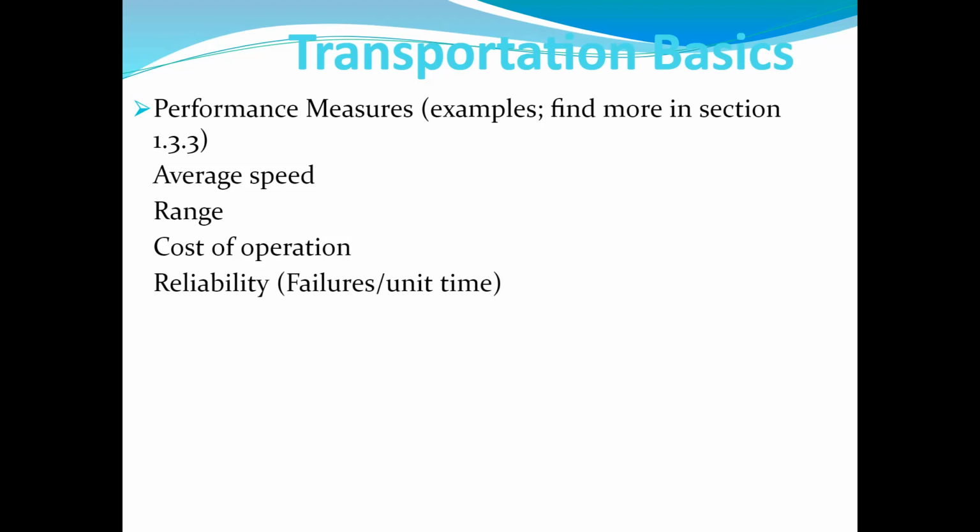There is a sort of evolution of the transportation system that's happening that contends that in the urban areas, because we design it for cars to move for the most part, even that 30th hour is way over designed, because for the remaining hours of the day, it encourages fast amounts of travel because we provide a high number of lanes, we provide wider lanes, and so forth. So even there is an evolution happening that is saying even that 30th hour is too much.